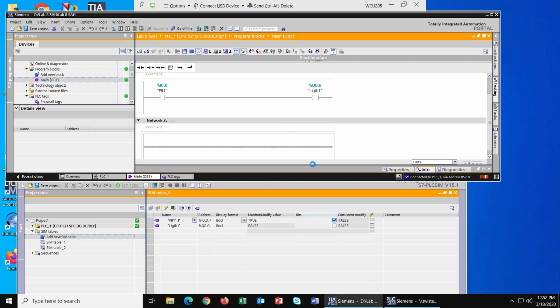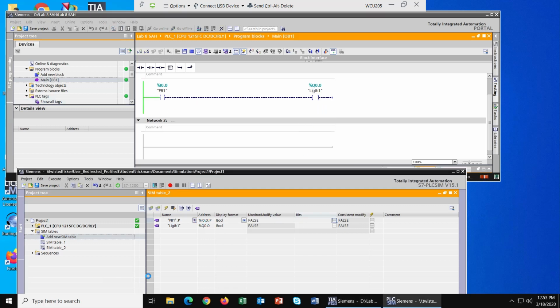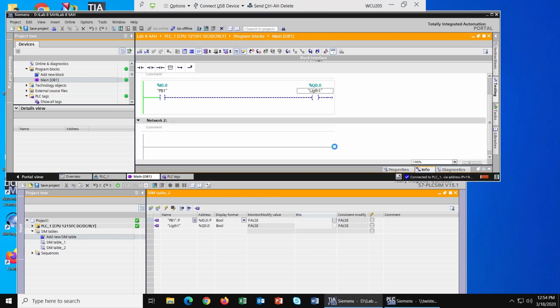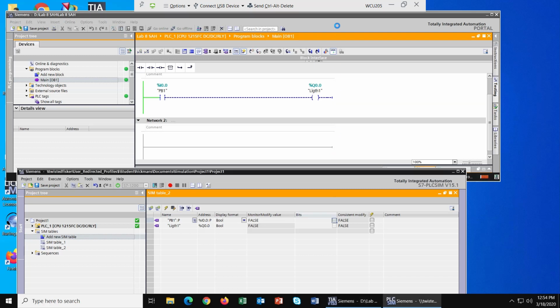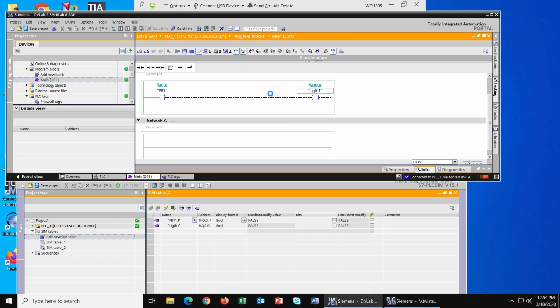And if you do that, you see that this did not come on. Hang on a minute. Let me find out what's going wrong. Okay, I just had to look at that a minute. Sorry. Notice once again, it's orange up here and orange up here. If you click into each one of these, it kind of makes that window active. So this makes the bottom window active. This makes the top active. So my problem here was it wasn't in run mode. So I got to hit the play button here, like start the CPU.